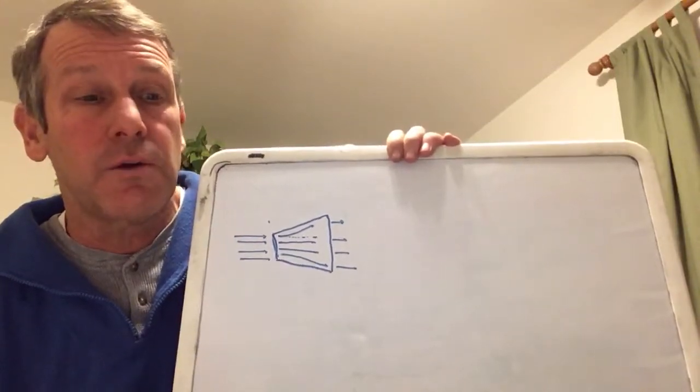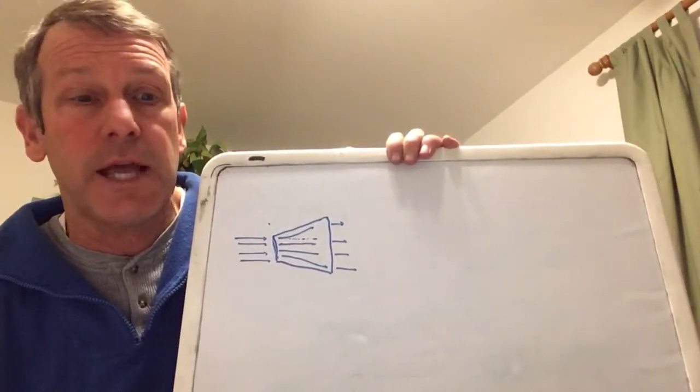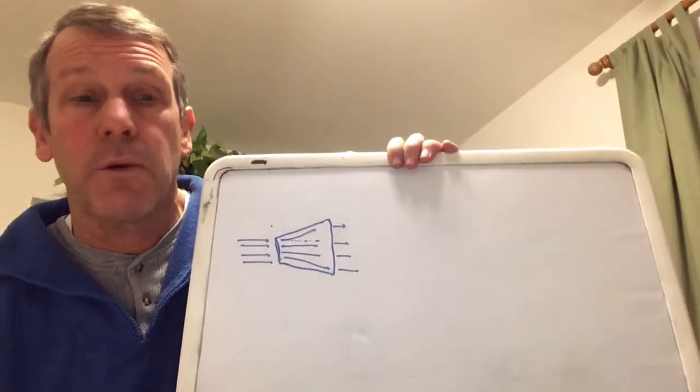All right, so I'm going to get a typical example up there, and we're going to think about how we're going to wind our way through it. I'll describe it really quickly while I erase it. So we're going to do air on this one, okay, and we're going to have air entering an adiabatic diffuser. So you might want to write that down. I'll get that up here in just a second. Air enters an adiabatic diffuser. Okay, and we're going to have it going 200 meters per second at the inlet.